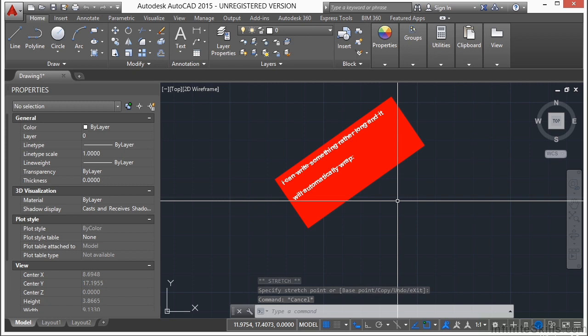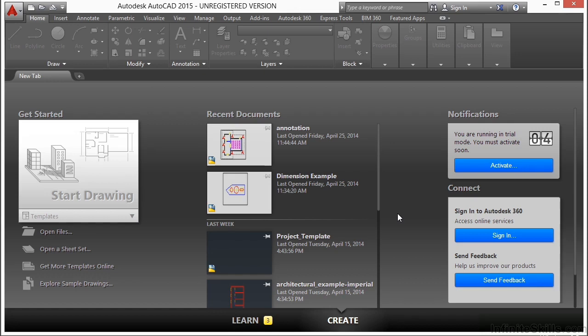So that's a real quick overview of multi-line text. It's very powerful, very word processor-like, and you can do a lot with it. Now, there are many different ways to use text, especially multi-line text. The method you will use will depend on your needs. Styles will control your font type. M-text objects can be edited within the text editor, but keep in mind that once you do, you lose some editing abilities. Let's just start with a blank file.